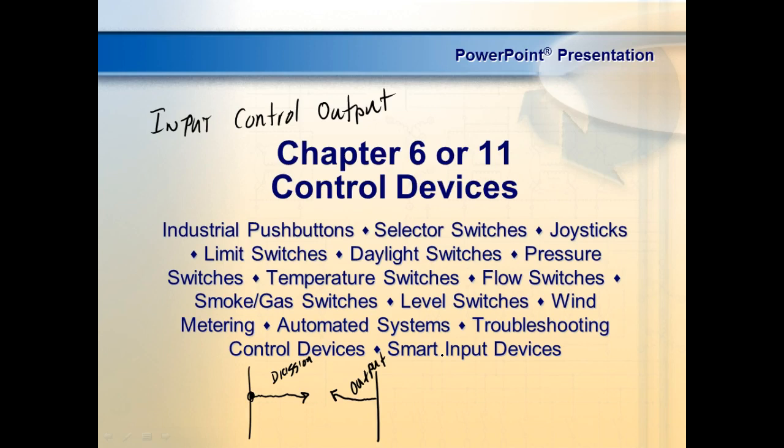We can put relays, we can put solenoids. And some very, very small motors, because the control section is not intended to run power, it is intended to make all your decisions, right? So that's your control. That whole ladder diagram that y'all are wiring up, that's the whole control circuit. That makes sense? Everybody okay?